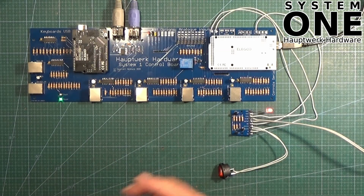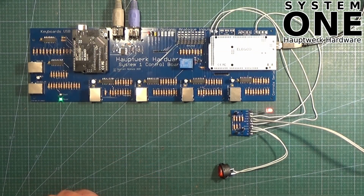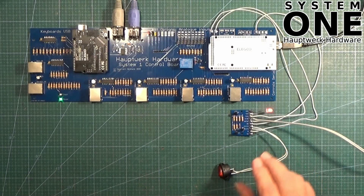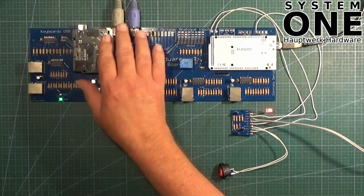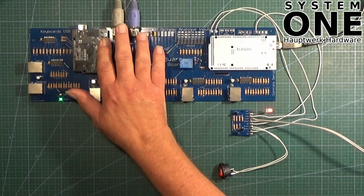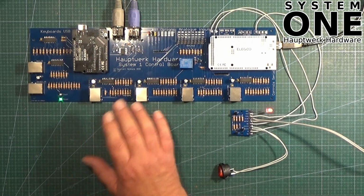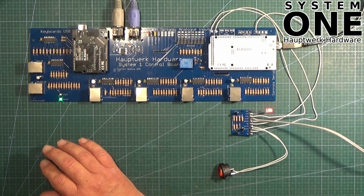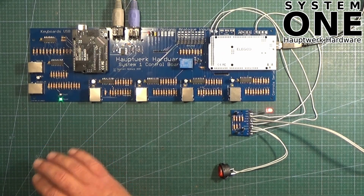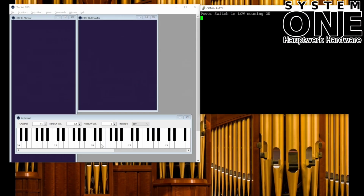So at this point we imagine that the computer's happily booting up, and when it's finished booting up and ready, the Raspberry Pi, or whatever computer you've got this on, with Hauptwerk or whatever, will send a MIDI signal to the control board telling it that it's booted up and it's ready to play. And the MIDI signal in question is on channel 11, and it is note 100, which happens to be E6 on the keyboard.